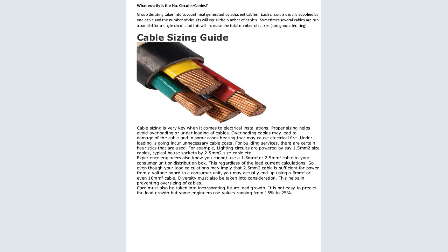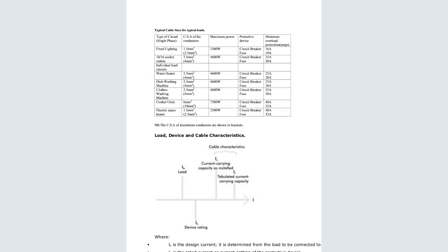We normally don't have 3 and so on in between there. We just go direct to 4.0. So if you think that your 2.0 is enough for now, then you can give room for the future and ask yourself, what other load growth is expected in this room? When you realize that load growth is expected in the room, you anticipate for the future and extend the loading, meaning you increase the cable sizes.